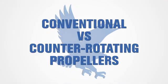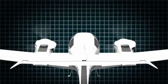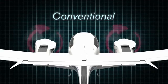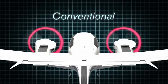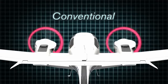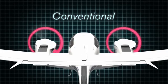Conventional versus counter-rotating propeller installations. Earlier, we had discussed conventional and counter-rotating propeller installations. Conventional propeller installations have both engine propellers rotating clockwise from the pilot's seat looking forward. This is the same direction the propeller rotates in the Cessna 172.